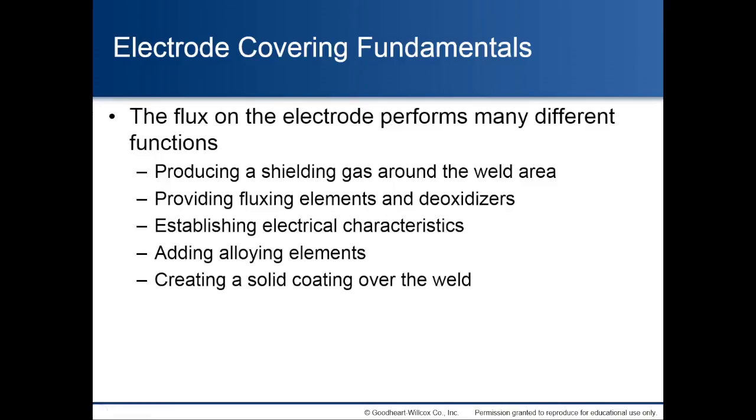Electrode covering fundamentals. The flux on the electrode performs many different functions, producing a shielding gas around the weld area, providing fluxing elements and deoxidizers, establishing electrical characteristics, adding alloying elements, and creating a solid coating over the weld.